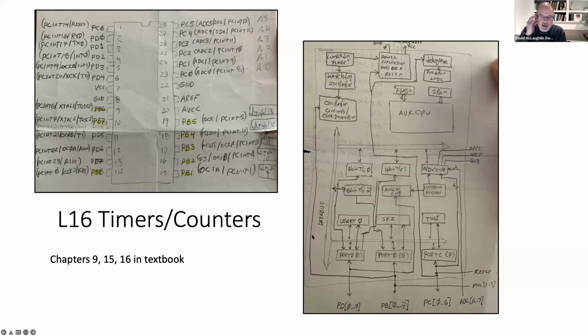And today we're going to cover yet another peripheral in the 328P, and it's the peripheral that gives us a timer or a counter. And we'll use this for making some sounds, for controlling speeds of motors, controlling the brightness of LEDs. I'll also use it for counting external events like reading distances from a sonar. So we're going to use this for a lot of different things.